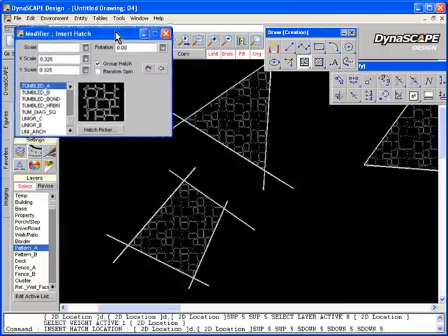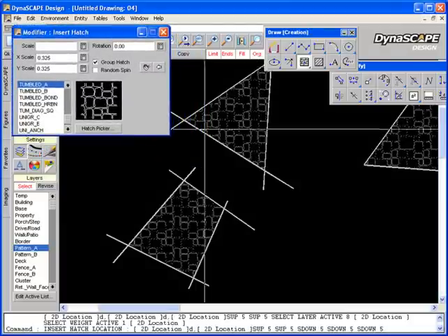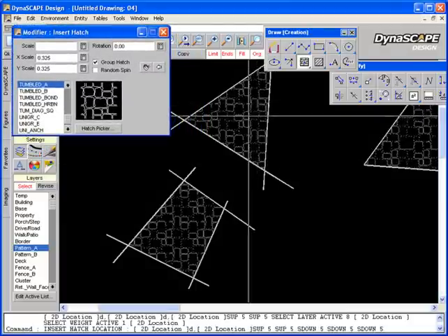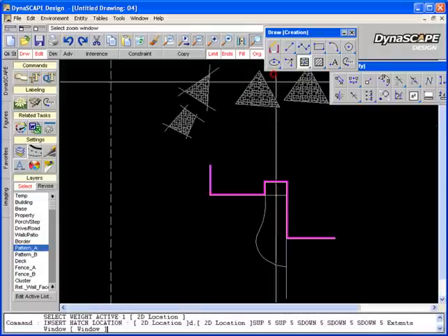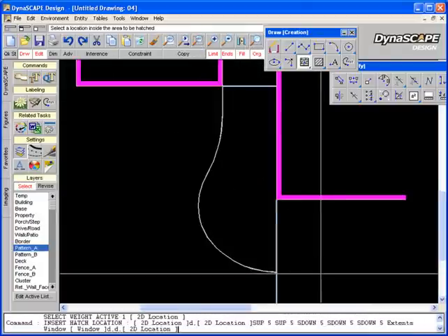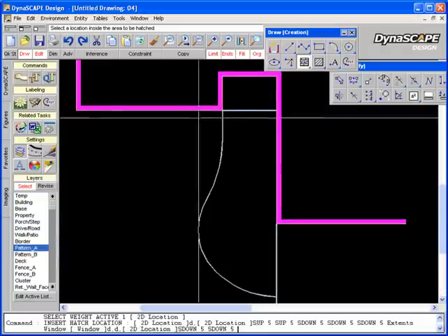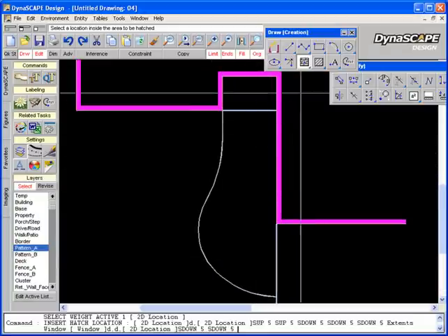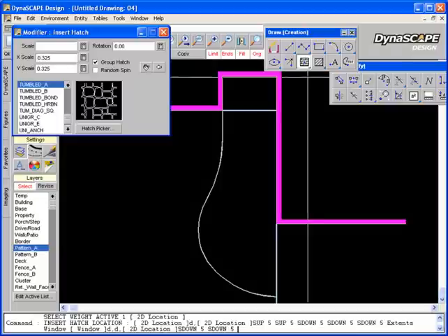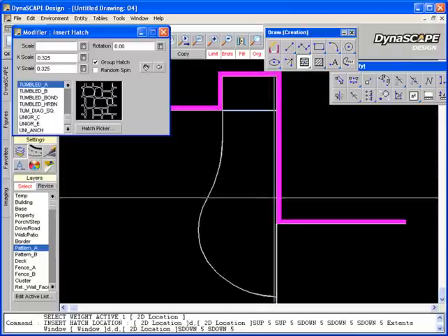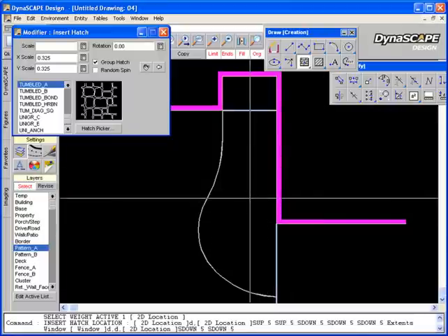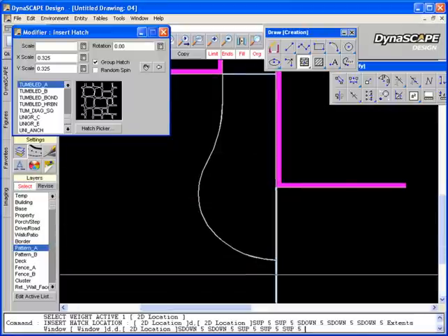The easiest way to do it when you're first starting out is to create that temporary closed area on the temp layer. For example, I have a walkway like this one down here. It's made up of a number of different shapes. Now I've drawn this accurately, so this tool with the blue dot in the center will work here because I know that I've drawn it correctly where I've got all closed corners, even though they're all made up of different lines and lines that go beyond each other.